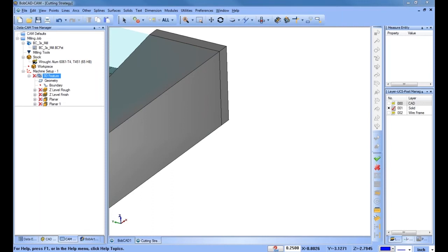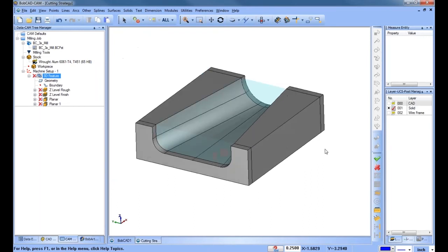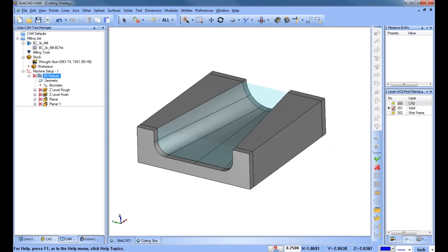You can use boundaries and add lines and stuff, John, when you're dealing with boundaries outside of the part, and we're going to get into that in just a second. So at this point, we talked about geometry selection, the importance of how that affects where your toolpath is being driven, boundary control, how you use a boundary to control where your toolpath is being generated, and then we have top and bottom of job, how we can control the levels, where it starts cutting and where it would end cutting.